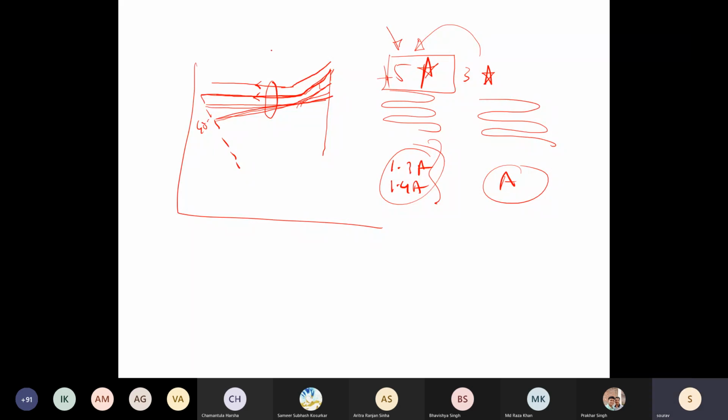Yeah, because that is finally setting your evaporator and condensing temperatures and hence the pressures. So if your evaporator temperature goes low for the same refrigerated space temperature, so let's say you want to maintain 16 degrees in a particular room. In a 3-star AC, your evaporator temperature could be of the order of 7 degree, whereas in a 5-star AC, your evaporator temperature could be of the order of 10 to 12 degree. That is a huge benefit. So now your compressor will work across a smaller delta P.